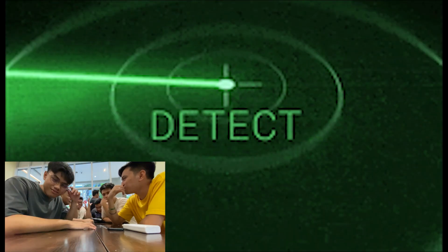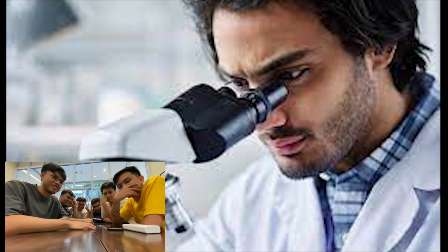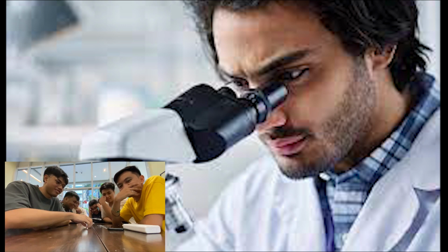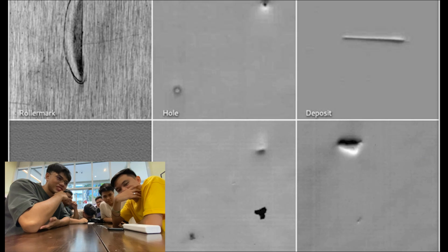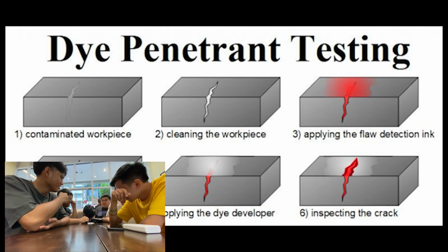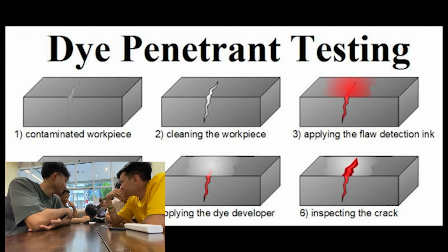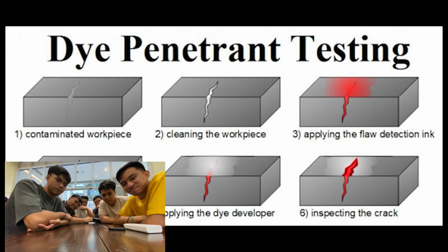Detection: a popular technique for identifying stress corrosion is visual inspection, in which specialists search for telltale indicators like visible damage on the material's surface, crack propagation, and initiation sites. This can be reinforced by employing methods like dye-penetrant testing, in which a surface is treated with a dye, and the dye's penetration reveals any cracks.